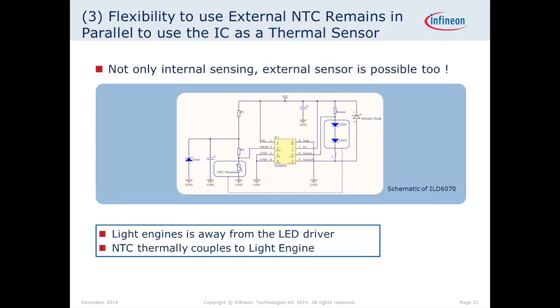In those cases, you need an NTC or PTC, and this ILD6000 family allows the flexibility to use the NTC as well. You don't have to if you can thermally couple, and you can save costs. But with the same IC, you don't need to change to another one when you cannot thermally couple the product.